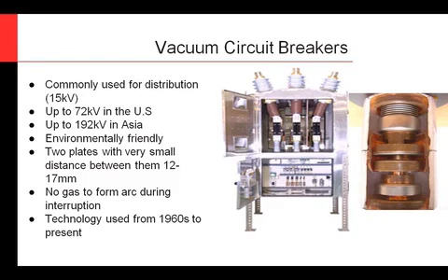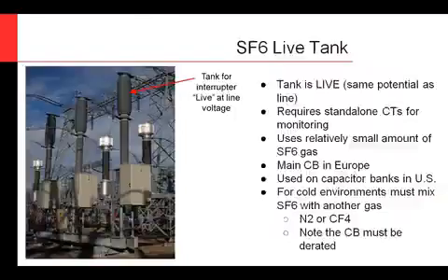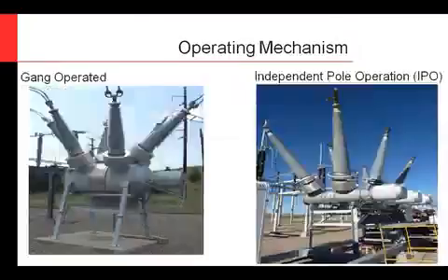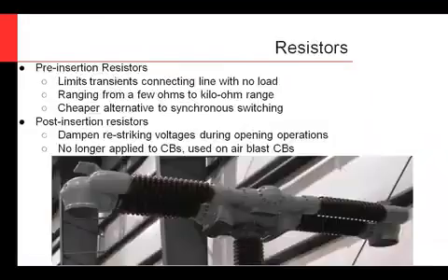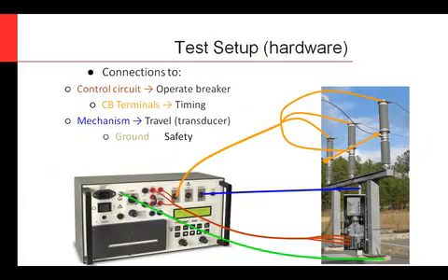I've seen maybe an SF6 circuit breaker that they're using at like 32 kV or something, but it's usually like a 72 kV design. They went down because they needed higher fault interruption current. You'll also see, and I don't have a good picture of one, some oil circuit breakers that are a lot smaller. They're all in one tank that can be used for distribution type. But those are, of course, older designs that are no longer manufactured.